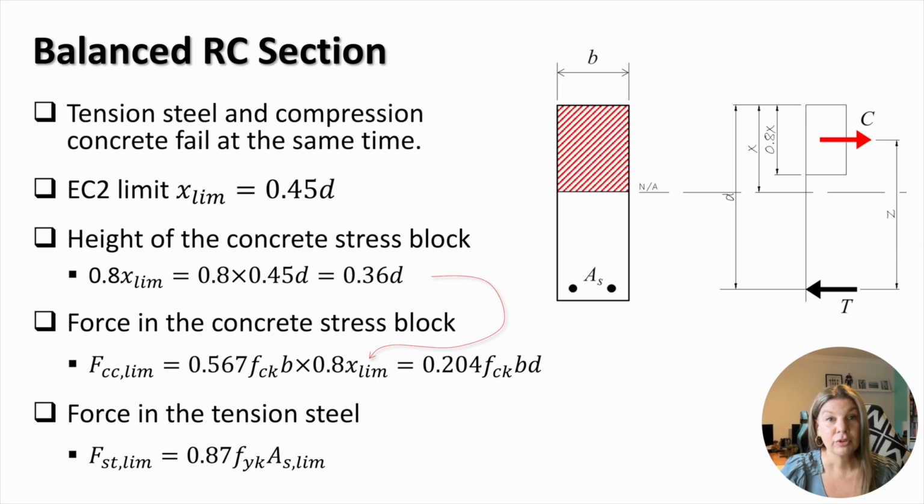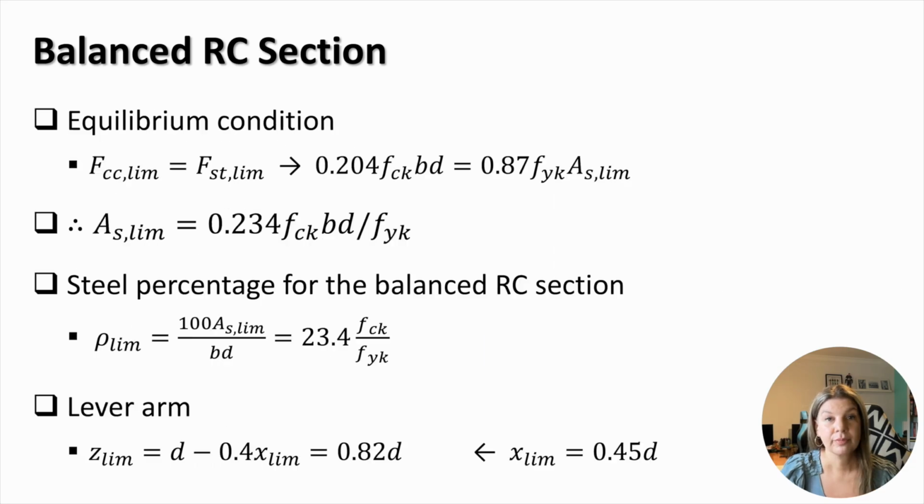For a designed reinforced concrete structure to remain in equilibrium, each part of its cross-section has to remain in equilibrium. The planar force systems shown on the top right corner should satisfy three equilibrium equations: the sum of forces in the vertical and horizontal directions, and the sum of moments. The sum of forces in the vertical direction is satisfied automatically due to the absence of vertical forces. The equilibrium in the horizontal direction is satisfied when the compression force in concrete equals the tension force in steel.